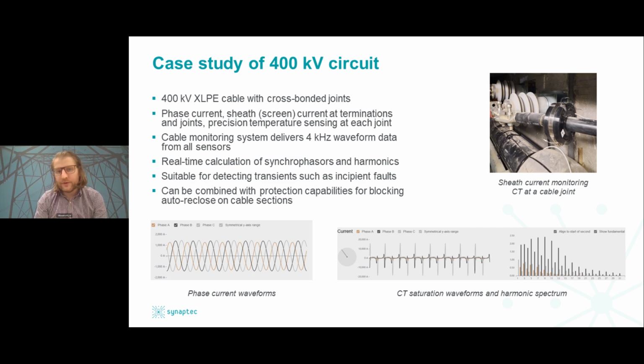And as we know for high voltage cables and grids, I think it's about 57% of outage time is due to the joints or terminations. It's due to issues at those locations. So that's exactly where we're targeting our measurements to give this much needed intel.